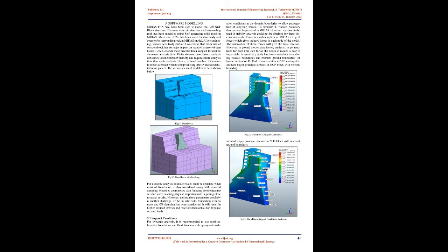When the induced tensile stresses on the upstream face are less than the following permissible tensile stresses, there is no requirement of reinforcement in concrete: load combinations A and B, no tension; load combination C, 0.01 FC; load combination F, 0.02 FC.